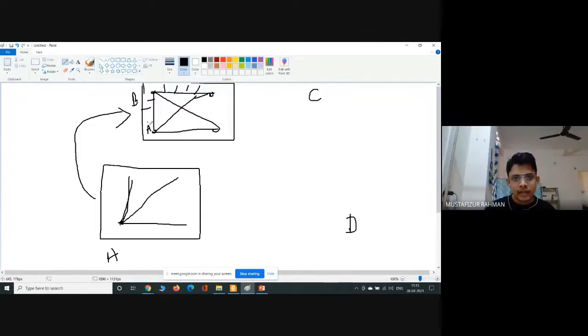Okay. Then this may go to the C point. When it goes to the C point, the lines from the C will be checked and drawn. Okay. Then we will be measuring all the necessary points from this C point. So this way. So plane table is very easy, very basic.